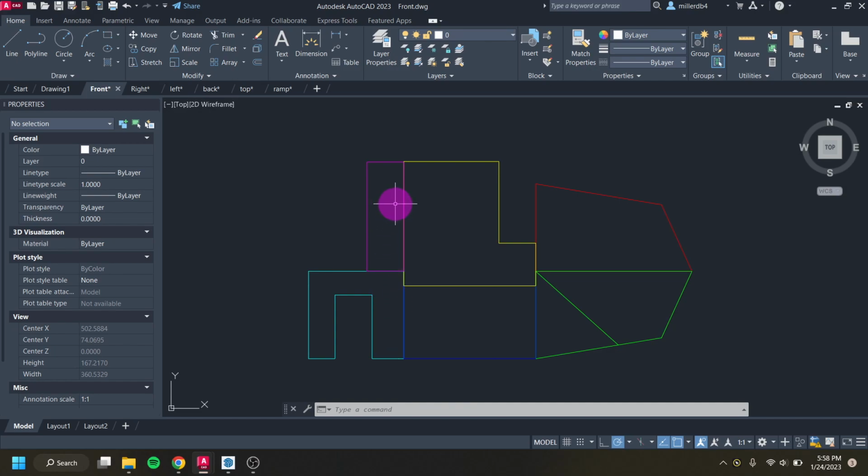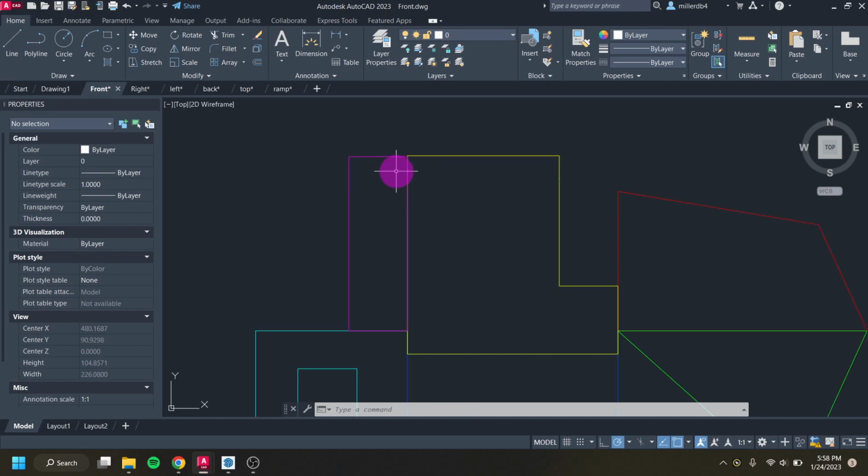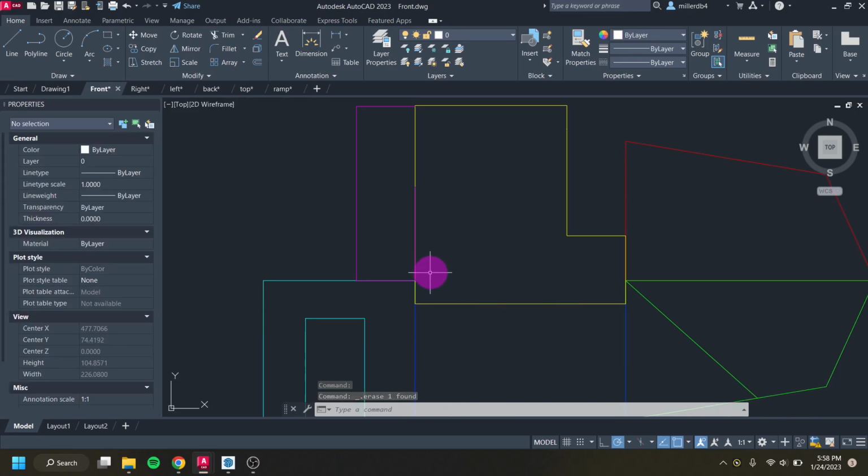So I have faces sharing the same edge, but if I just take them from their bare bones of that export, the laser is going to go over edges multiple times. So we have here this magenta edge, and the laser is going to travel and cut along that magenta edge. But if I click on that one and delete it, we can see that this yellow edge is also hiding underneath it.